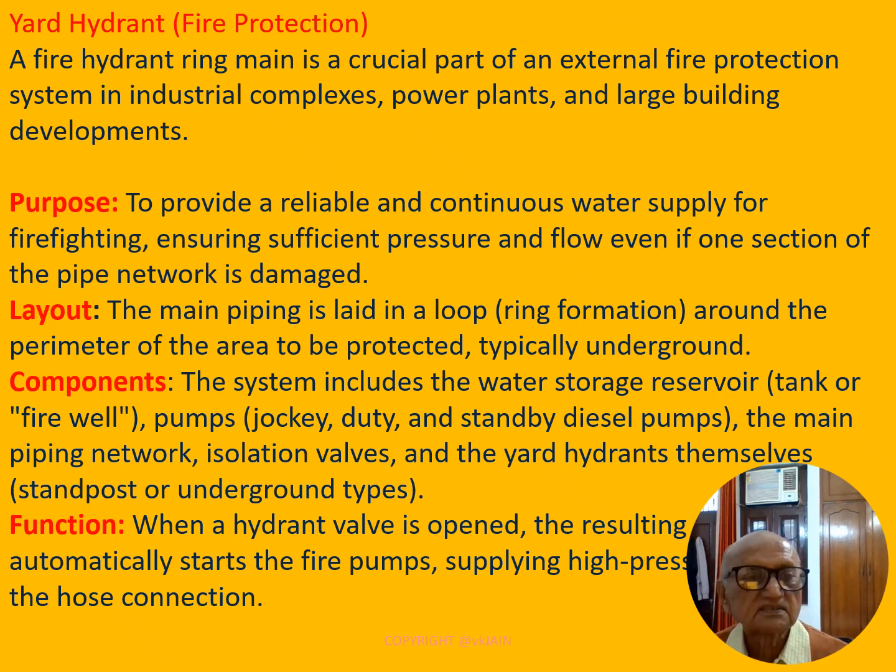Friends, in this particular slide, we'll deal with the different aspects of the yard hydrant system. Yard hydrant system is always external and it is designed in a ringmain fashion for fire protection in industrial complexes, power plants, and large building developments also.